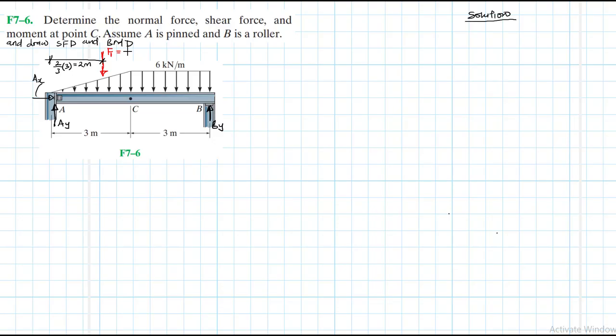So this is just going to be equal to the area under the loading diagram for the triangle, which is just half, times the length, which is 3, times the maximum height for this triangle at this point. This maximum height there is 6. So this therefore gives us 9. This is 9 kilonewtons. Great.